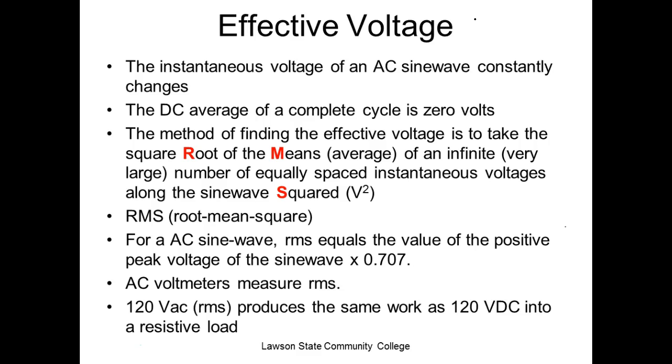Now, most AC meters measure RMS by using this value right here. And it works great for sine waves. Don't understand that? Yes or no? If it's not a sine wave and you don't have a meter that has the ability to do that, then it's not going to measure the correct value. So we have another type of meter that costs considerably more. But odds are you don't need this meter unless you work on variable frequency drives and that kind of stuff.